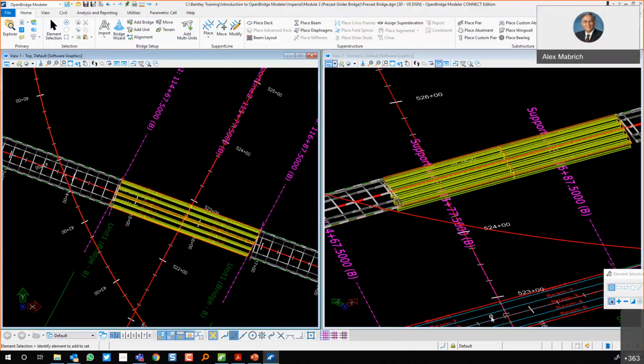Yeah, Denison, can OBD detail variable deck thickness? Yes, it can do that, because remember, the same as we generate the width of the deck as a variable, if I activate thickness by station, I can just go with different thickness along the alignment of that bridge. So yes, I can do that. It's just a matter of applying the proper variable to it. However, LEAP will not calculate that, because LEAP doesn't handle variable thicknesses. So it will use the minimum thickness to do the calculations in LEAP. But for modeling, yes, you can, and it will provide you as well with the proper quantities too.